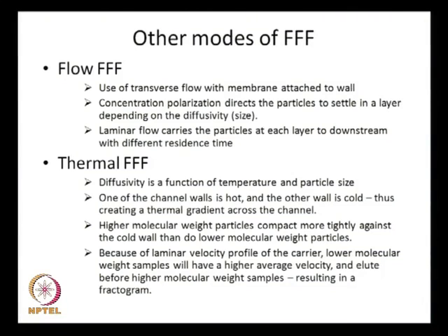There the bottom wall and the top wall are at different temperatures. Okay. So, diffusivity is a function of temperature and particle size. If one of the channel walls is hot and the other wall is cold, thus creating a thermal gradient across the channel, then you can accomplish this thermal FFF. Now, here higher molecular weight particles compact more tightly against the cold wall than lower molecular weight particles, and again because of the laminar velocity profile of the carrier, lower molecular weight samples will have higher average velocity and elute before higher molecular weight samples, resulting in a fractogram.